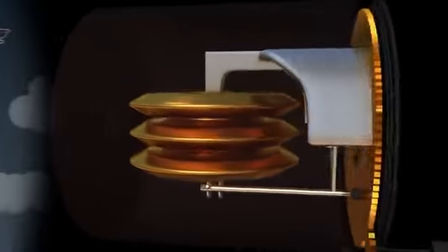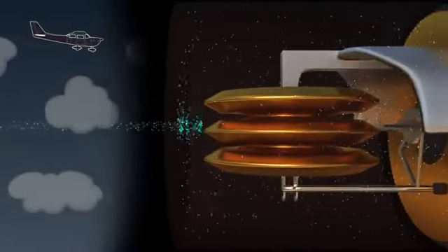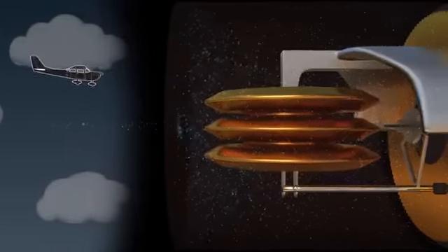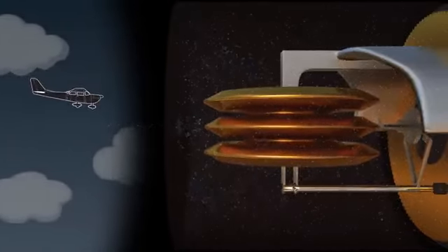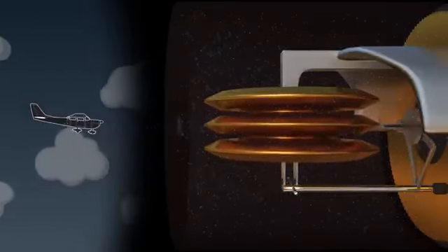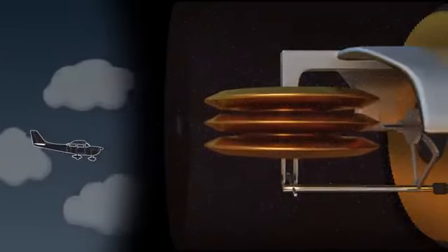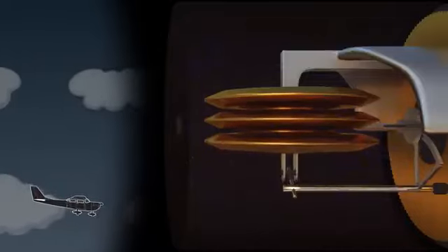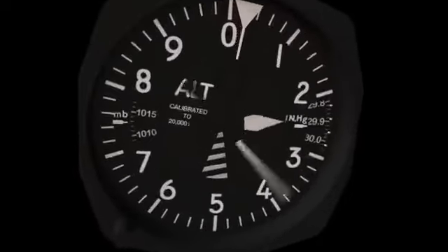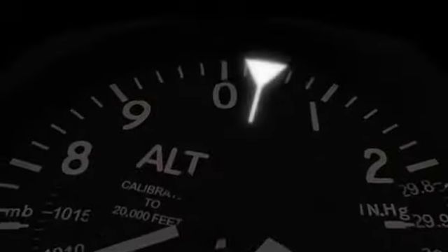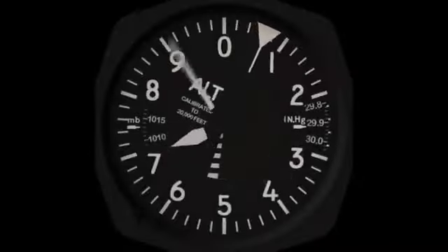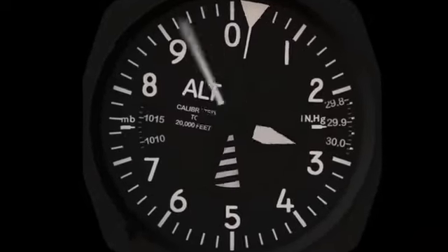Now, when the airplane descends, the opposite happens. Descending to a lower altitude results in higher static pressure. Air from the static port will now enter the case of the instrument and squeeze the aneroid wafers until both the case pressure and the wafer pressure are equalized. The mechanical linkages will then rotate the hands on the face to show a lower altitude. The face of the altimeter contains three hands, the 10,000 foot, 1,000 foot, and 100 foot hands. These hands move clockwise and counterclockwise to display the appropriate altitude.